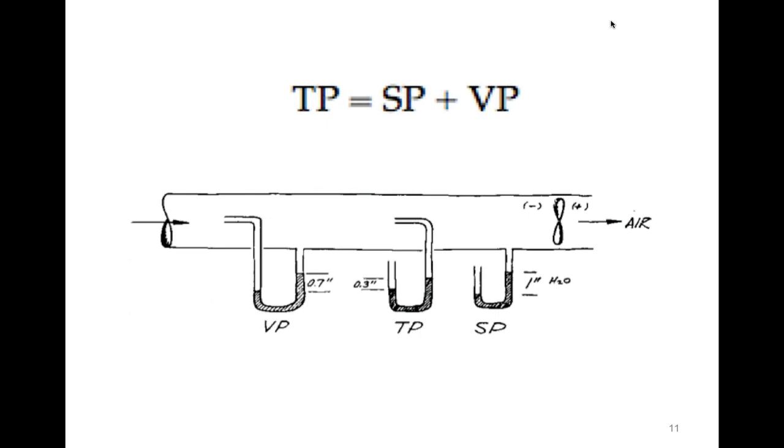If there's no fan operating in the duct, the absolute static pressure is 14.7 pounds absolute, or 0 psi gauge. Pressures in ducts are not much different than standard pressures, right? Because in a large duct, it's hard to build up a lot of pressure. It's not like we're filling a cylinder under hundreds or thousands of pounds of pressure like we might fill a cylinder with nitrogen or carbon dioxide. So the pressure differences between one side of a fan and another side of a fan are not that great.